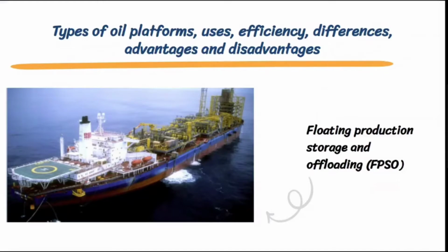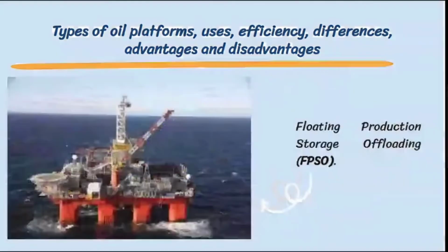Most FPSOs have been built by retrofitting and converting large tankers that have dynamic positioning systems. These systems allow a boat to maintain a certain position or direction using its own thrusters and permanently measuring and comparing its position with respect to the reference position.